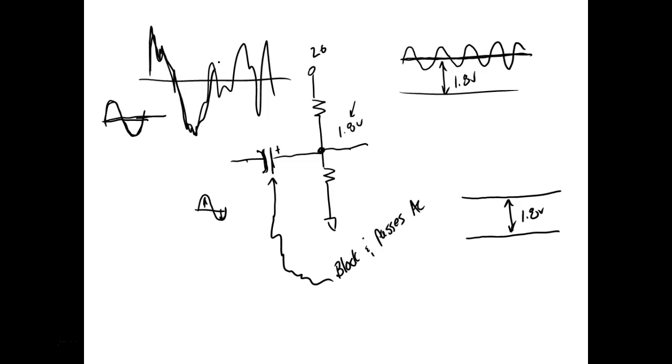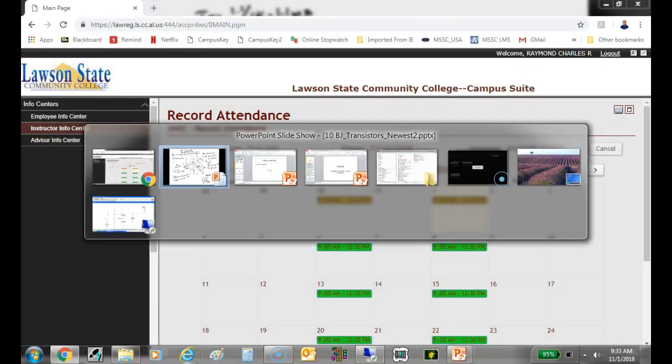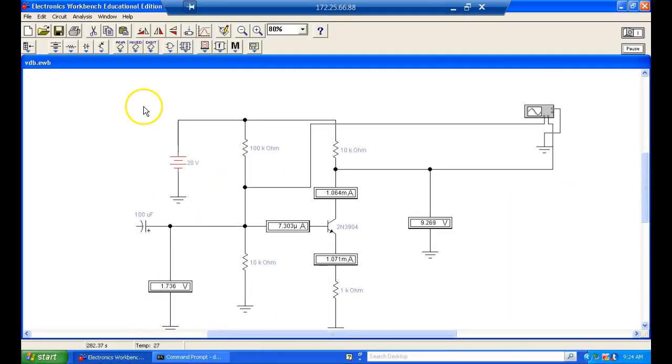Because what's going to happen? And if your bias is screwed up, then that means something's going on. We'll look at what's going to cause the bias when we accidentally saturate this thing or accidentally cut it off. So I can come over here and put a sine wave in on this thing, and we'll see the DC bias. It'll change a little bit, but it's not going to change much to square around with our calculation.